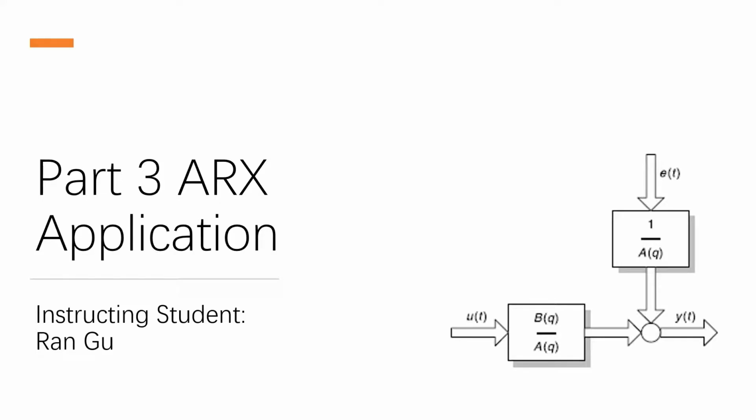Then, using the output displacement data and the input force function, we can back-calculate the transfer function generated by the ARX function in MATLAB. The conjugate roots and the residuals of the transfer function can be used to compute the modal frequency and mode shape. Then the mass, stiffness, and damping matrices of the system can be calculated, as well as the comparison of the displacement plot.